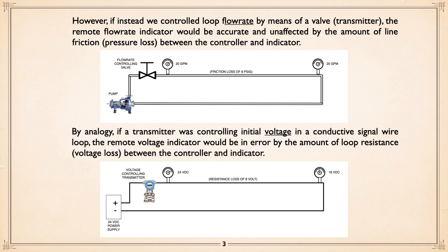Well, if you read 24 volts right by it, you say, well, that's its full output. You're going to find out at the end of this long line, it's reading 16 volts. So it's going to say, oh no, the controller has brought it down, or the transmitting signal has gone down quite a bit, when in actual fact it hasn't.